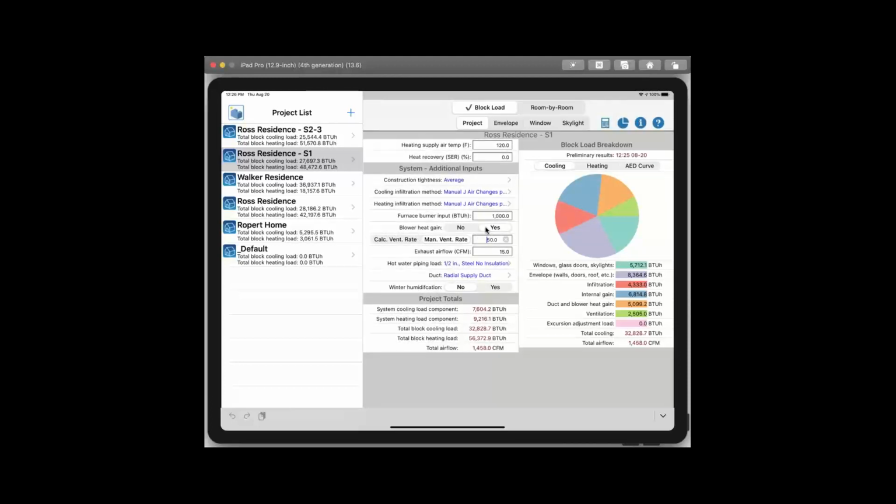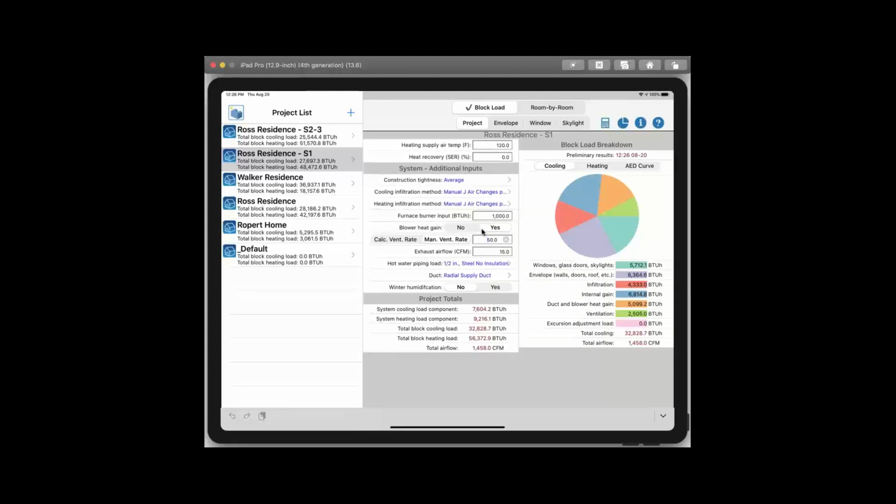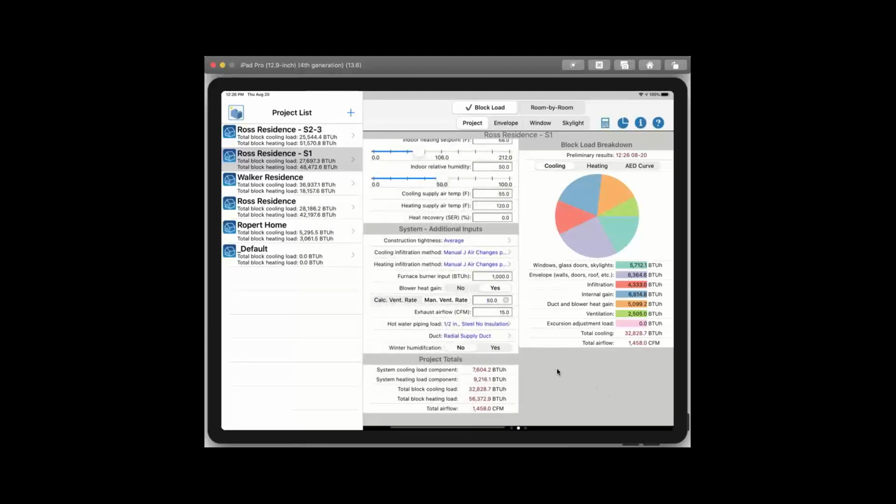So it doesn't calculate the 62.2 ventilation standard? Oh no, it does not. This does not do 62.2. We actually used to have a separate app for that, but I don't think it's available anymore. So if we calculated it, let's say it was 60 CFM continuous, we'd put it there instead of 15, we'd put 60 there. Is that correct?